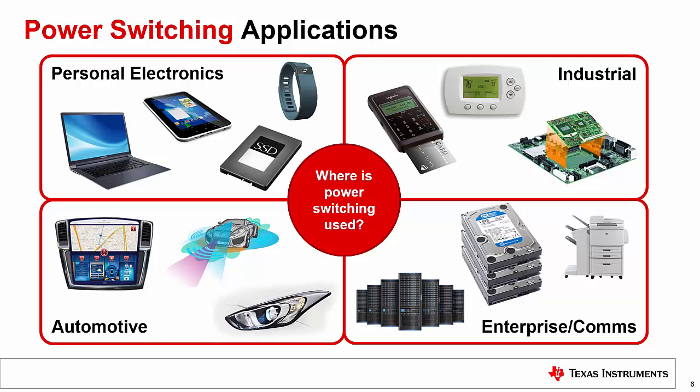Automotive uses power switching for power sequencing the applications processor in infotainment and cluster applications. Power switching can also be used to turn on and off the headlamps of a car. In the enterprise market, servers need power switches to control the system startup. Each server has many hard drives which must be powered. To prevent stress on the power supply, switches are used to turn on a few hard drives at a time, and this will allow the power supply to gradually turn on safely.